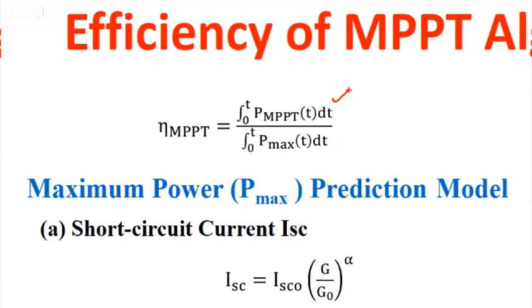That is what efficiency, power, voltage and current will be the output of the MPPT. There I can measure and multiply. You will get the MPPT output. Now I have to see what the panel output is. What output should come, because that depends on the irradiation falling on it and the temperature of the panel, what should be the maximum power.